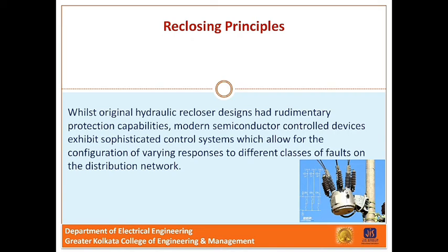The most common fault type of an overhead distribution network is lightning strike. Lightning surges cause an increase in voltage which can cause localized breakdown of the insulation, allowing arcing over insulators. Recloser can detect this as an overcurrent or arc fault. For lightning surges pass very quickly, so the first reclose operation of a recloser can be configured to both trip and reclose quickly. The first reclose allows for interruption of the arcing caused by lightning but restores the power quickly.